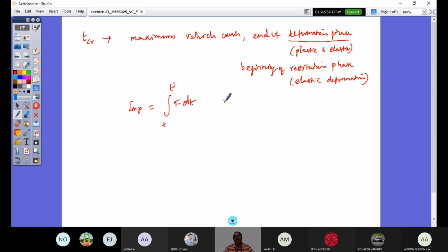Again, an important thing: the colliding vehicle, after it strikes the other vehicle, the brakes are released. So they are free, and their frictional impulse forces are negligible. So you can consider that along the line of impact, momentum is conserved. In the earlier derivation, the exchanged impulses cancel each other. That is why conservation of linear momentum is applicable along the line of impact. If the exchanging surfaces additionally have some friction, if it is not a smooth surface, then you have an external additional impulse, and the momentum cannot be conserved.